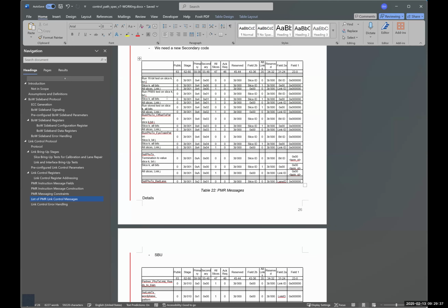Okay, we can leave that. Well, didn't we define a slice as 16 bits, or are we defining this? This is the pattern length bits. Oh, this is the individual LFSR bits. Yeah, individual bits. So this could go all the way up to 31 because we are supporting PRBS. The spec mandates 9 and 31 at the minimum, so I think that should be 31 bits at the minimum, if this is for PRBS.